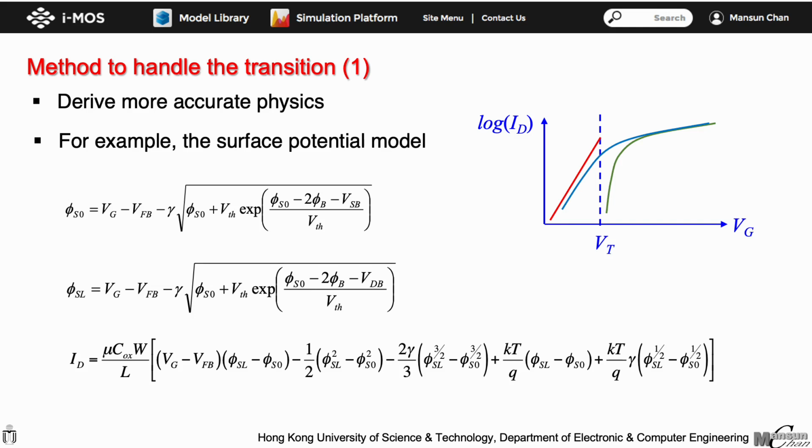Secondly, the complex form of the equation makes it difficult to adjust part of the curve while not affecting the other parts. For example, assume the turn-on region is accurately predicted already, and only the subthreshold region needs to be adjusted. It is difficult to change just some parameters to adjust the subthreshold region without affecting the on region.